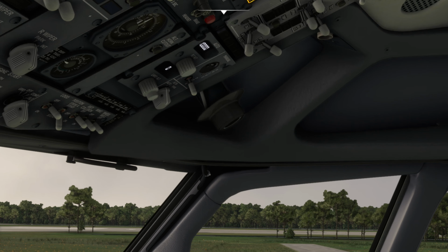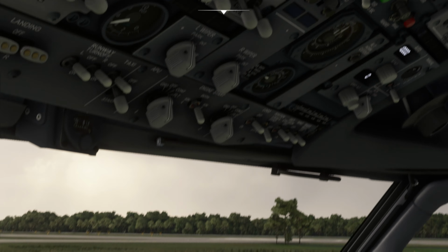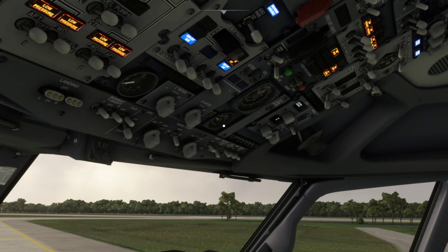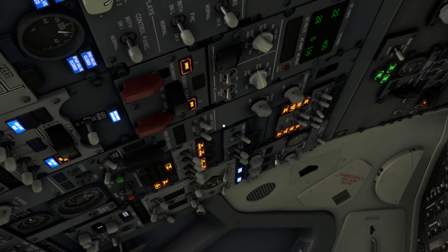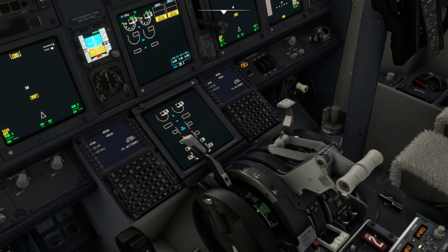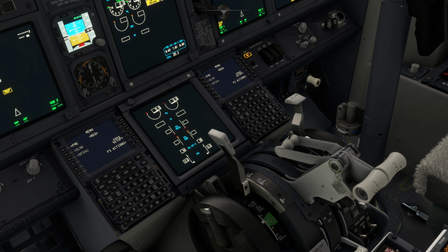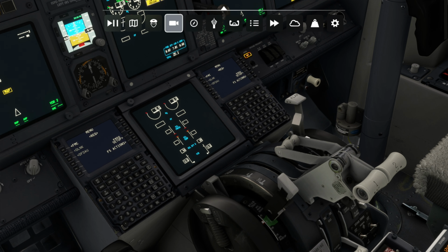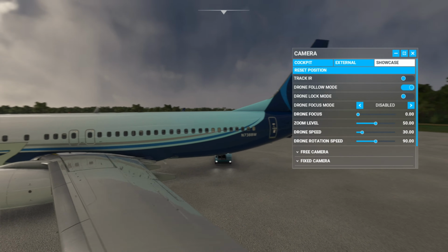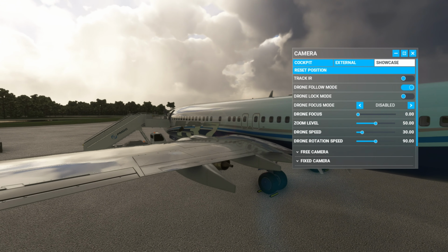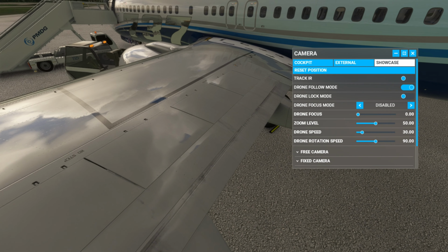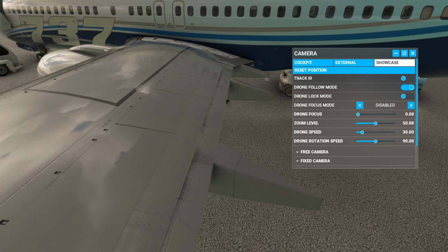That's cool. What we will also have is the ability to generate electrical power, quite obviously, but also the ability to generate hydraulic pressure. Right now we have no hydraulic pressure on the airplane, which means that no matter what I do with my spoilers, which are now in the full ground deploy detent, if we go out here on the upper surface of the wings, you'll see the spoilers are here, roughly center of screen. They are retracted. They're not deployed.